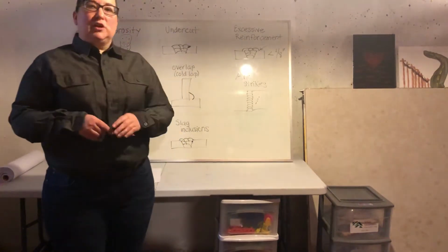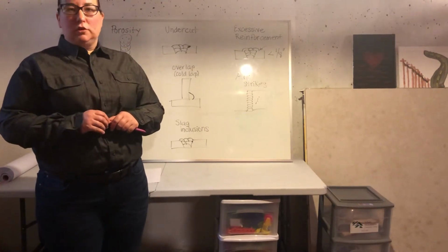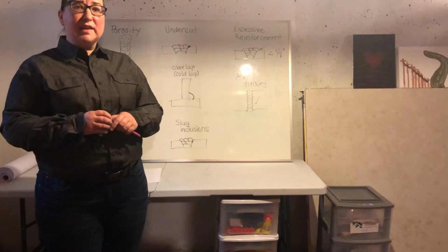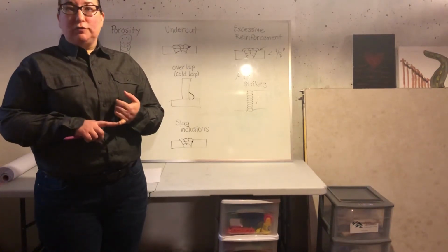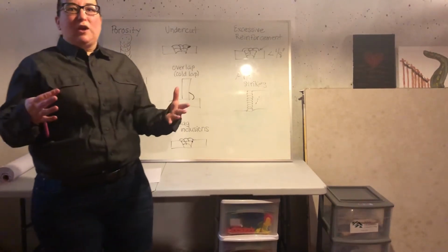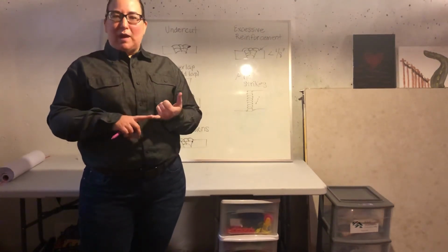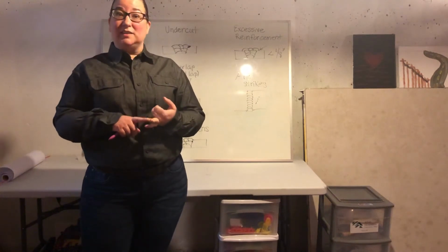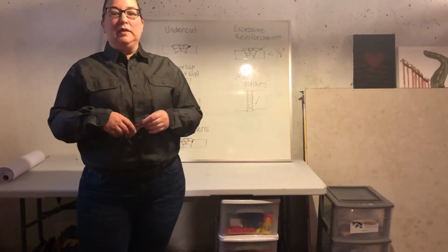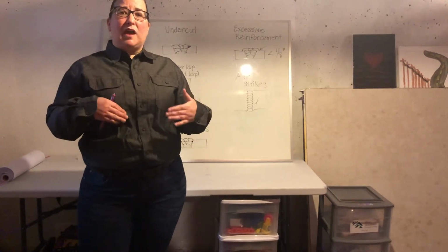So when we're looking at our machine, we want to make sure that we have the correct amperage set on our machine. There are some really good resources for this if you're trying to look for a baseline of what to run. ESAB makes a really great application for your phone. So does Miller. It's called Miller Weld Settings. These are really great to have a jumping off point for what you're going to set your machine at. So things you would put in, what type of metal are you welding on, and what size and type of electrode are you using, or the stick for this shielded metal arc welding or stick welding. So you take a peek at that and it would give you a range, and usually we want to start somewhere in the middle of that range.